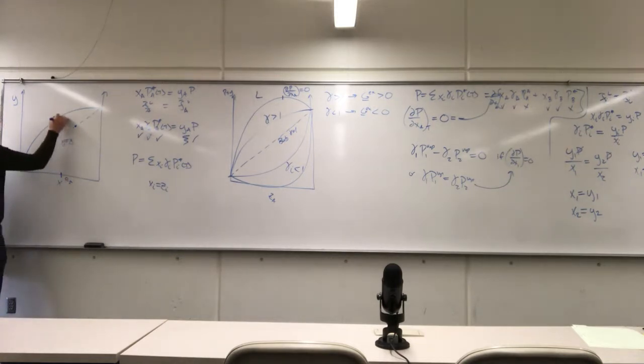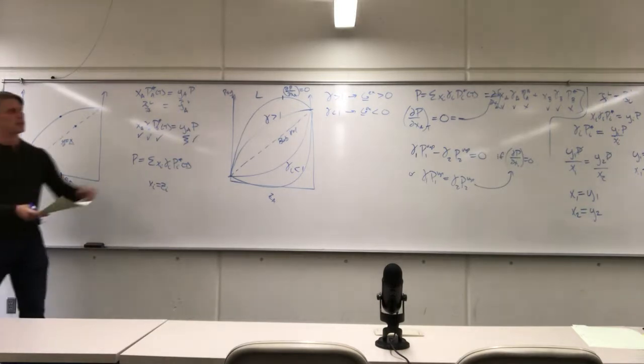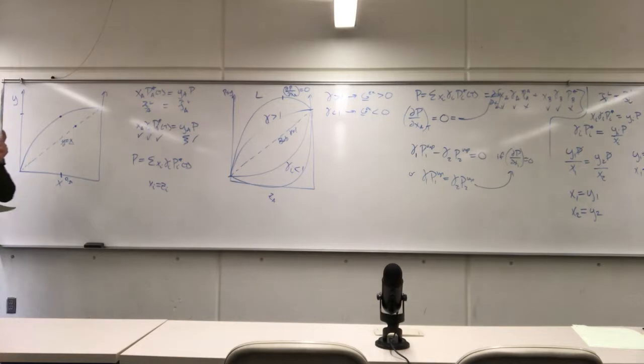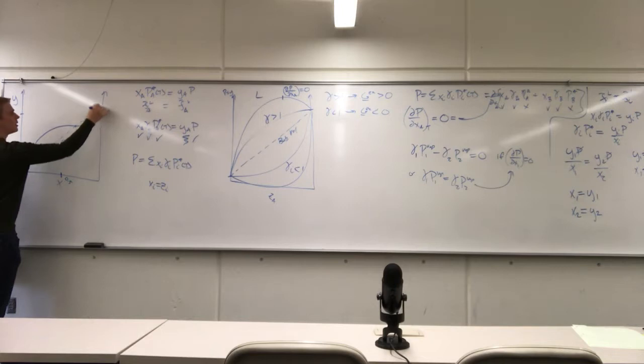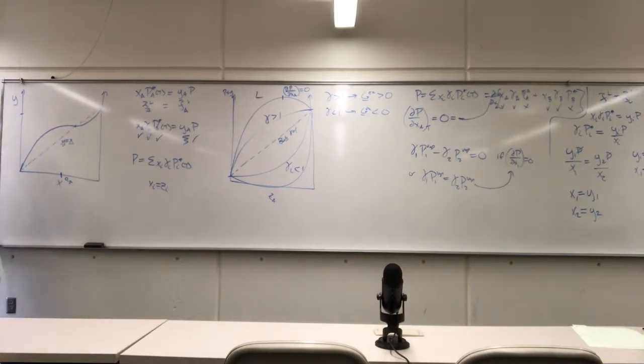And exactly that's the case here, right? This is obviously above the y equals x curve. Now if I have an azeotrope where x equals y, my liquid composition is equal to my vapor composition, that means that I'm no longer going to have a nice looking curve. It's going to go up, cross, and then go underneath.